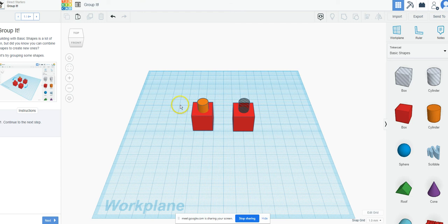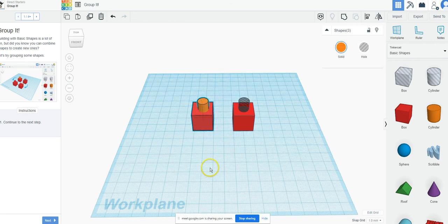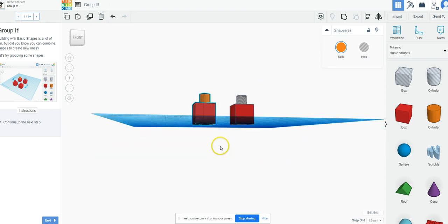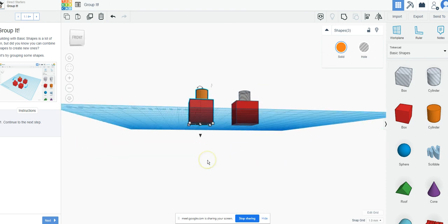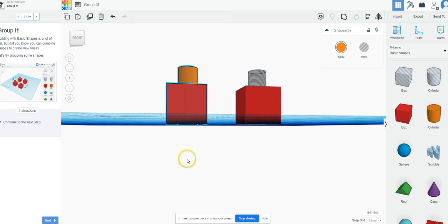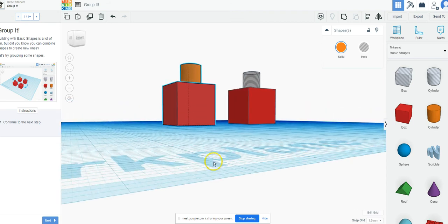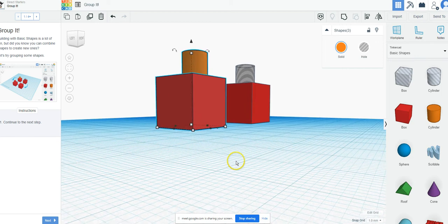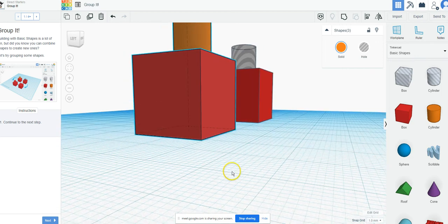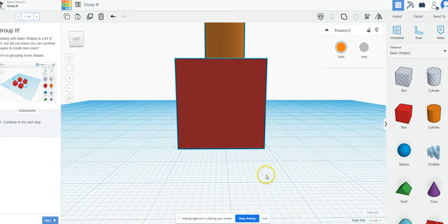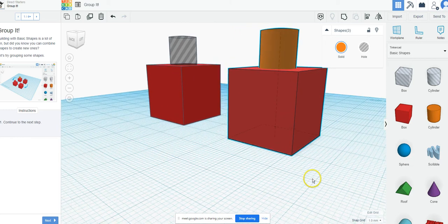So what Tinkercad allows me to do is to come along and draw a box. I'm just pressing my left button down, and I'm going to select everything. So I selected both the box and the cylinder, and it's a little subtle, so I'm sort of pointing this out to you. The box now has a blue line around its edge. If you look real close, you can sort of see that, right? That means I have selected the box. The blue line means the box is selected.